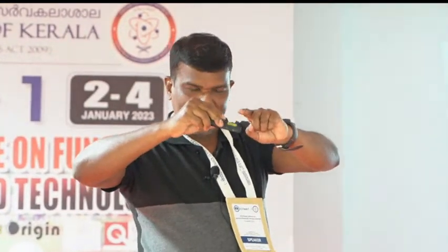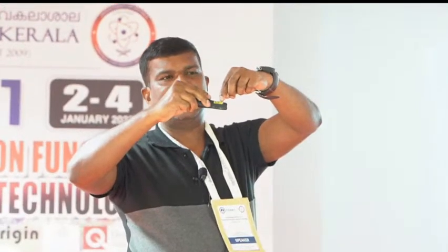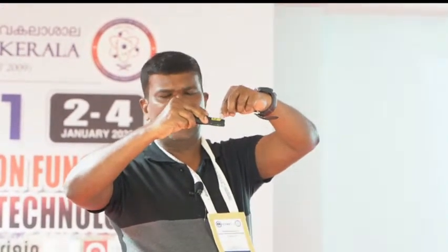So this part has to touch the substrate, which means it will always apply higher force to the substrate. And you need that higher force because it is higher than the electrostatic force. Once the force is high on the substrate, if the sample moves up and down by applying voltage, it will no longer be electrostatic. It will be only the PFM signal that you are supposed to see, right? So all the time, try PFM measurements by bringing the laser slightly inside, not at the end. The end never gives you the right PFM signal.